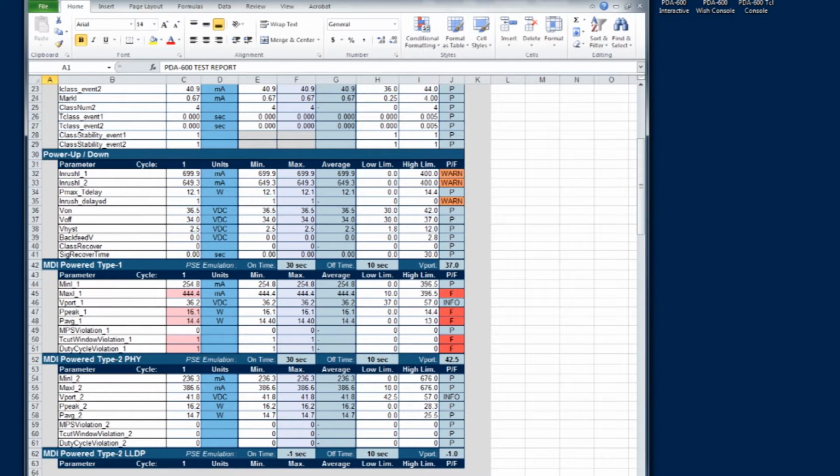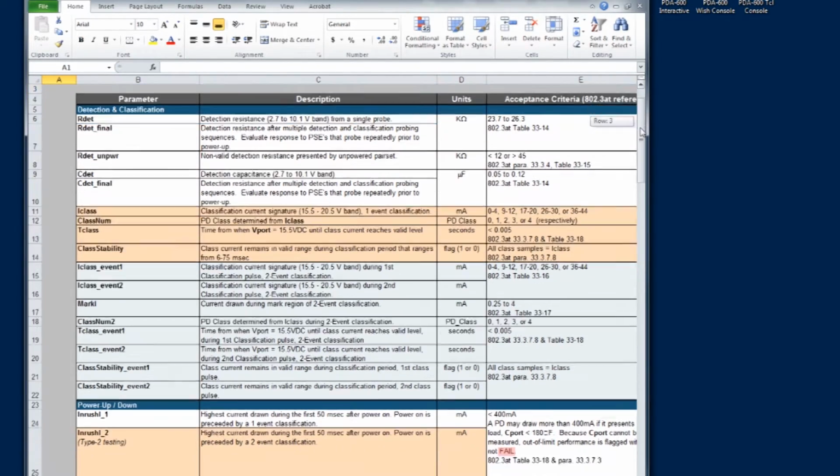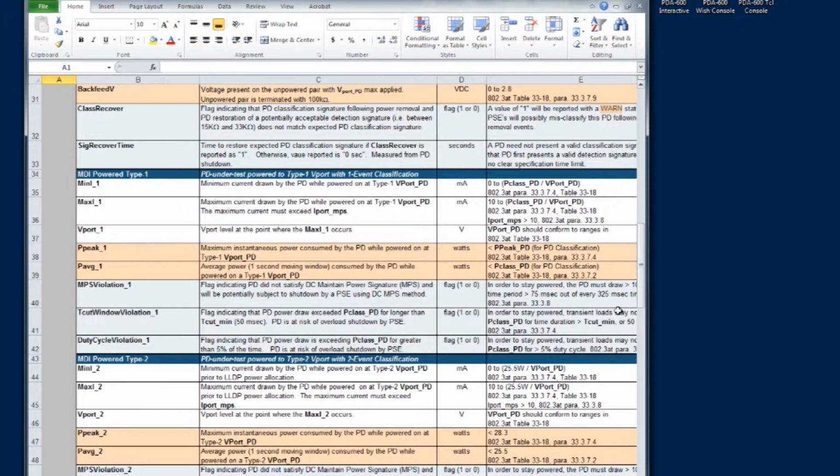Powered parameters then appear in each of the remaining subheadings. The other test report pages present the passive test parameters for the other 3 quadrants, namely Alt-A MDI-X, Alt-B MDI, and Alt-B MDI-X. A note page in the standard report provides some detail regarding each parameter included in PD conformance testing. Many are referenced to specific parameters and requirements in the 802.3 specification.